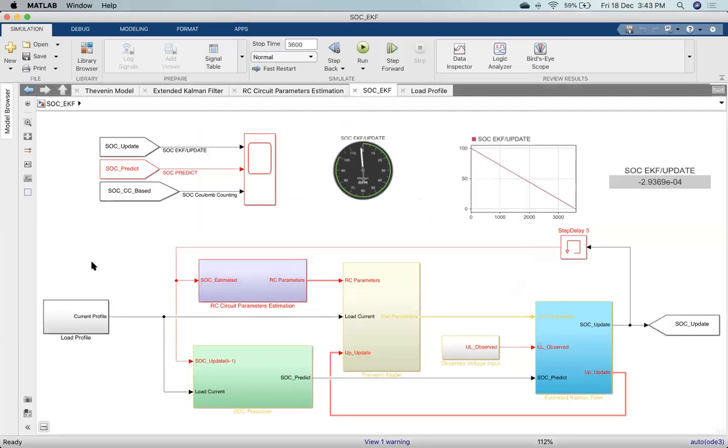So this is the Simulink model which I have developed. The previous graphs are from MATLAB coding, and this is Simulink based. What I can do is convert all these things into C code, and then dump it into a controller or the BMS that I'm going to develop. That option we have over here. We can convert all these things into C code.